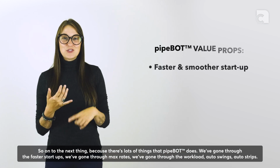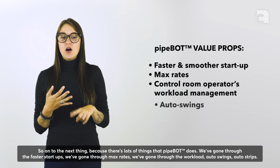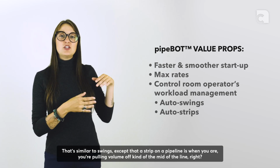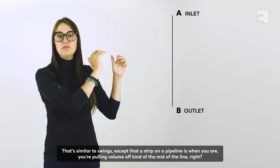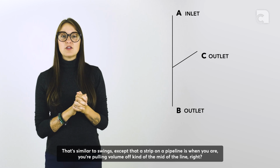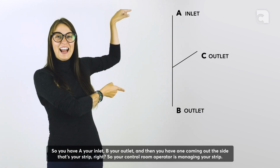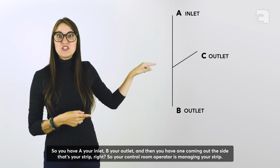So we've gone through the faster startups, we've gone through max rates, we've gone through the workload, auto swings, auto strips. That's similar to swings, except that a strip on a pipeline is when you're pulling volume off kind of mid of the line, right? So you have A, your inlet, B, your outlet, and then you have one coming out the side. That's your strip, right?